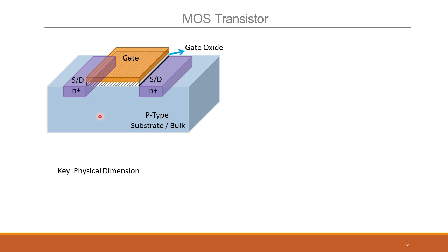In this case, since the bulk is P-type, you make it N-type here. And the channel is just formed below the oxide near the surface of the bulk, but not in the source and drain, because this is slightly doped compared to this, and this is the opposite polarity anyway. So the inversion happens here, the green thing that we see out here. That is called the channel.